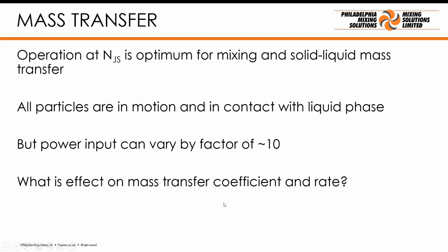So the next thing we want to look at is mass transfer. That's what we're trying to achieve between the particles and the liquid. Operation at the just suspended speed is the optimum for mixing and solid liquid mass transfer, if we're looking at solid liquid mass transfer. So all the particles are in motion and in contact with the liquid phase. And so Zwietering's definition is that the particles are not stationary for longer than 1 to 2 seconds.